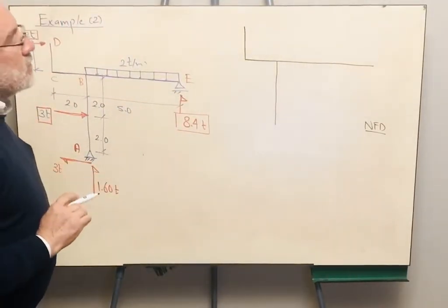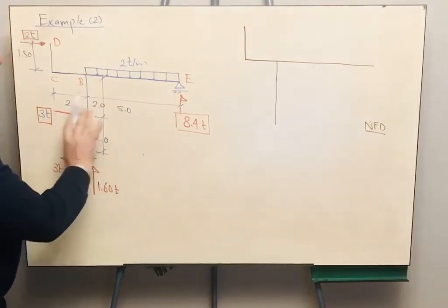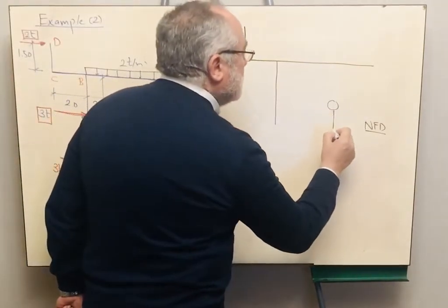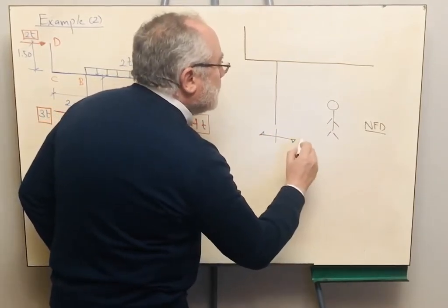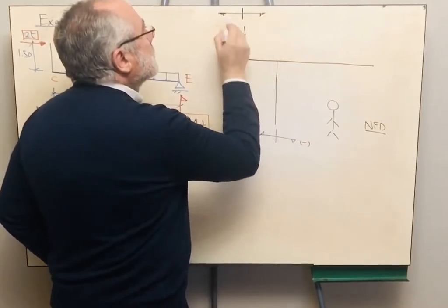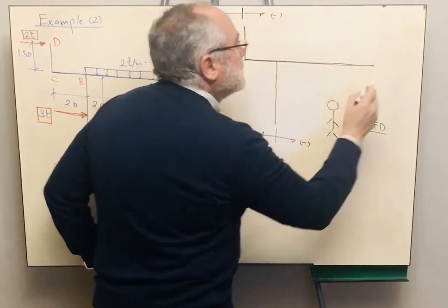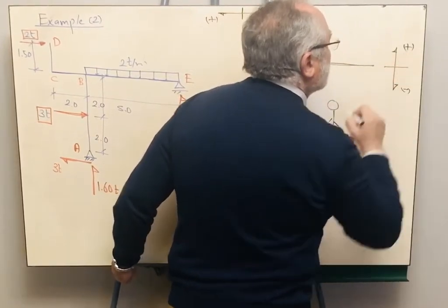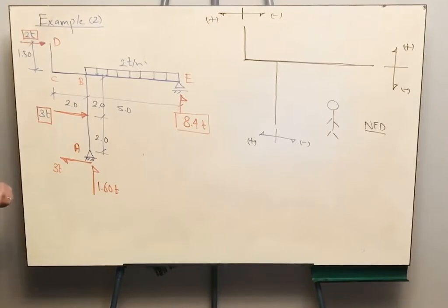Let us decide on the side where we are going to draw the positive and negative moment. Again, the frame is shading the right hand side, as if we are standing here, under the frame. It means that this is the near side and this is the far side. The near side is negative and the far side is positive. And of course, for this central line, the near part is below and the far side is above. Let us start part by part.